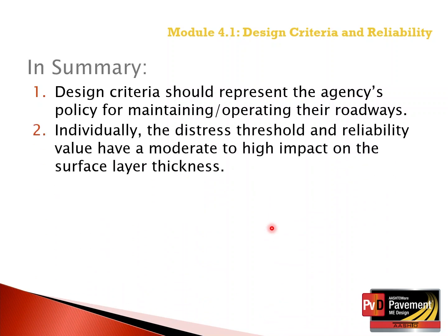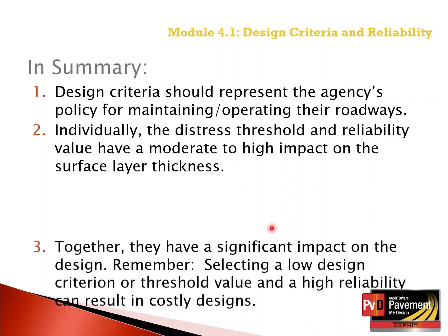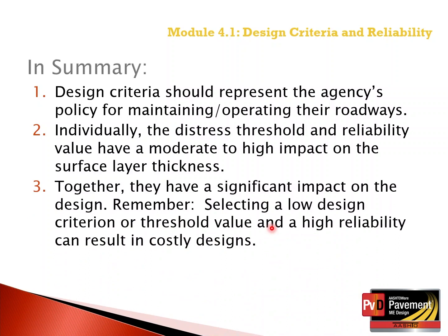The second outcome or summary is that individually the distress threshold and reliability values have a moderate to high impact on surface layer thickness. Together, they have a very significant impact on design. Remember, selecting a low design criterion or threshold value and a high reliability will result in very costly designs.